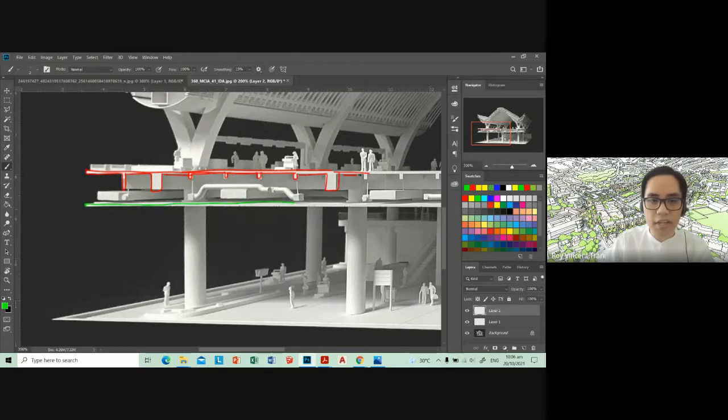Typically, when I was in first year, I just thought the ceiling and the floor slab were the same thing, but they're two different things. Really, the purpose of a ceiling usually is to hide these mechanical ducts and systems. So this over here, I'll just color it pink, is a duct, usually for air conditioning. This is how big they are. They're around 0.2 to 0.3 in depth, let's say 0.4. And then width, they can range anywhere from 0.6 to 1 meter.